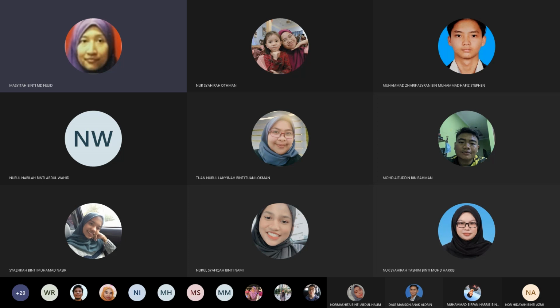So please be careful when you have the W for each slice, whether it is located on the right of the O or at the left of the O. If you have the W on the right side of O, the alpha is positive. If you have W on the left side of O, the alpha is negative. What is the O? O is the center of the slip circle, whether you have a tension crack or you don't have a tension crack. Any questions?